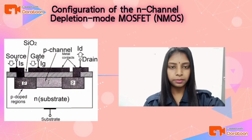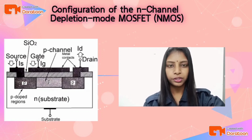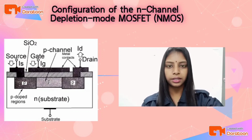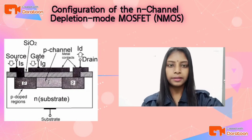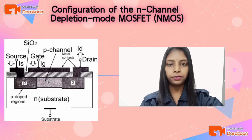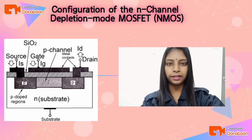The figure beside me shows the depletion type MOSFET. I'm going to explain the device configuration of the depletion type MOSFET. The channel is made up of N-type material and the substrate is P-type material. Through the metallic contact, the drain and the source terminals are connected to this N channel, and similarly the gate terminal is also connected to a metallic contact. If you observe here, there is no direct connection between this N channel and this gate terminal.